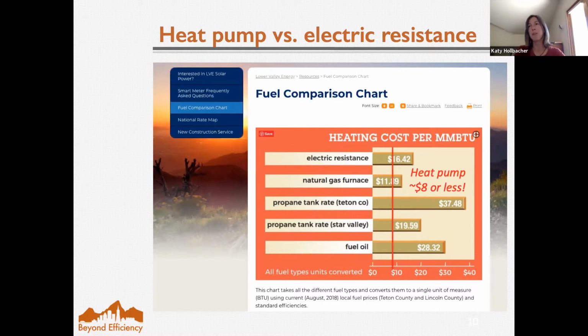So if we use heat pump technology, even in our cold climate, where heat pumps, when you get down to pretty cold temperatures, are less efficient and potentially will get to the point where they don't even work, and you then have to do electric resistance, still on balance, being very conservative, if electric resistance is costing $16 for a certain quantity of energy, you can be spending half, if not even 2/3 less, depending on other aspects of the project, on heat pump technology. So we would really love to see a lot more effort being put on heat pumps in this climate.